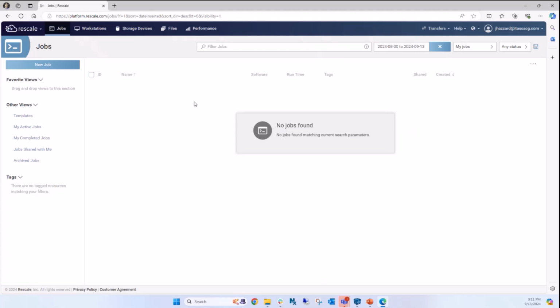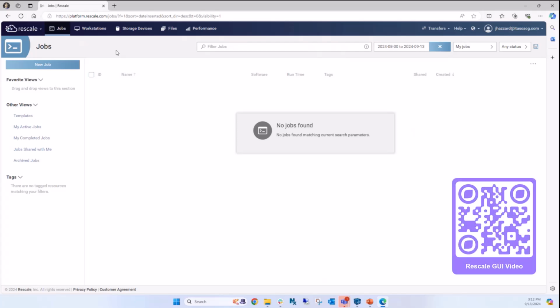Once you log in, this is the screen that you see. What you can see across the top here are different things that you can do, and the most important ones are jobs and workstations. Workstations are if you want to run FLAC3D in the traditional way with the GUI on a single computer and look at it as you're doing the calculations. We have a separate tutorial about how to do that. It is also very easy to run FLAC3D on the cloud using a workstation system like this, and this allows you to run the GUI version of FLAC3D.